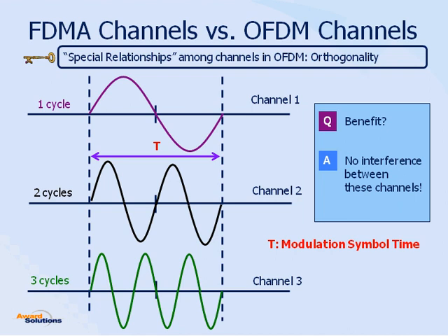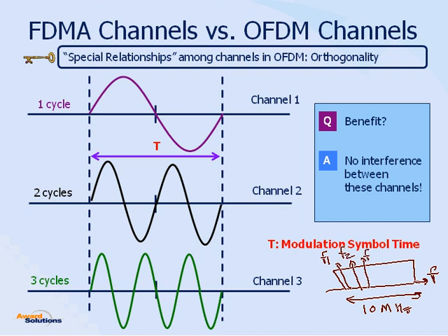Okay, now let's take a simple example. I have some bandwidth, maybe 10 megahertz, and then I will divide it into several subcarriers. So I have one subcarrier F1, another F2, yet another F3, and so on. So let's look at the first subcarrier F1. And the goal is to construct orthogonal subcarriers. Let's pick some time period, 66 microseconds.